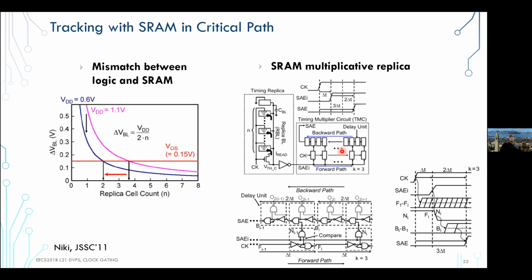overall supply voltage? Because if you think about it, if I change the supply voltage on the memory, on a read, the cell that's pulling down basically has a reduced drive. So it will need more time to get the bit line to a certain voltage that you can actually sense with the amplifier. The sense amp is also going to be affected because the lower its own supply voltage, the more of the input voltage it needs to compute in a given amount of time, right? So you need somehow to track all these things, or at least be able to configure them, right?